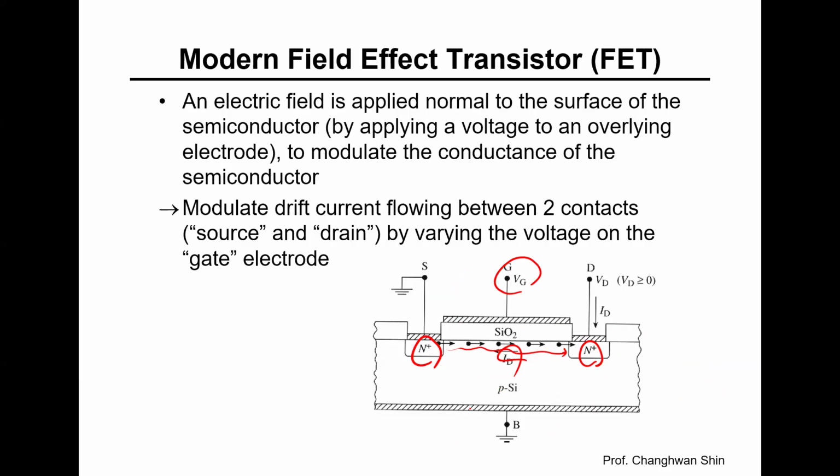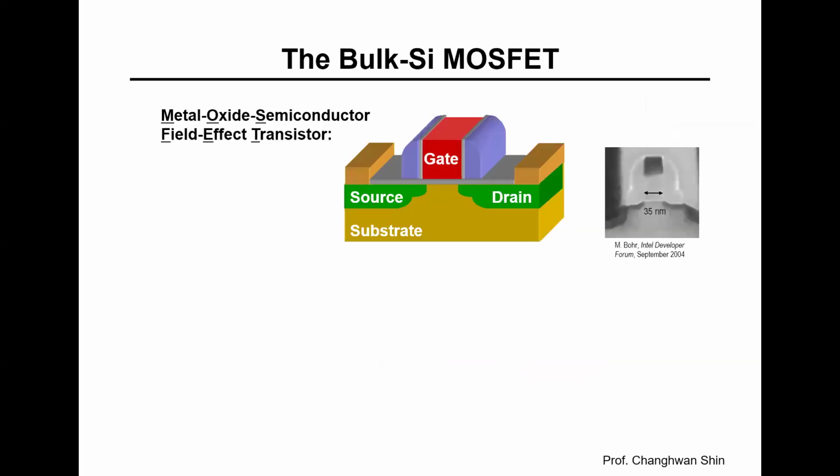However, you are controlling how much water flows from the pipe to the sink, right? In MOSFET, from source to drain. In similar fashion, the gate voltage creates an electric field that either allows or restricts electron flow through the channel, without the gate current directly entering the semiconductor. Okay. All right. So that is the main working principle.